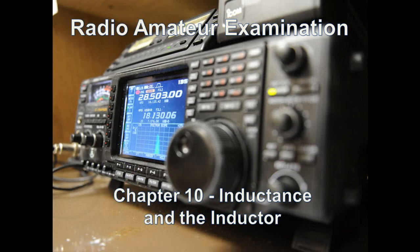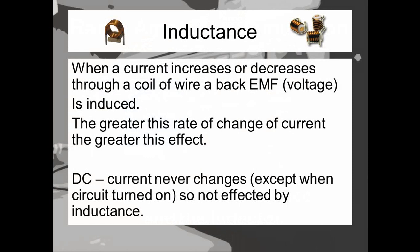So next up we had a look at inductance and the inductor. So what is an inductor? Well, unlike a capacitor, which is two plates, an inductor is basically a coil of wire. And when a current increases or decreases through a coil of wire, it creates a voltage called a back EMF in the coil. Because of the way the magnetic field surrounds the wire, as the current increases, that magnetic field increases, and as that magnetic field increases, it creates a voltage in the opposite direction, effectively acting like a brake.